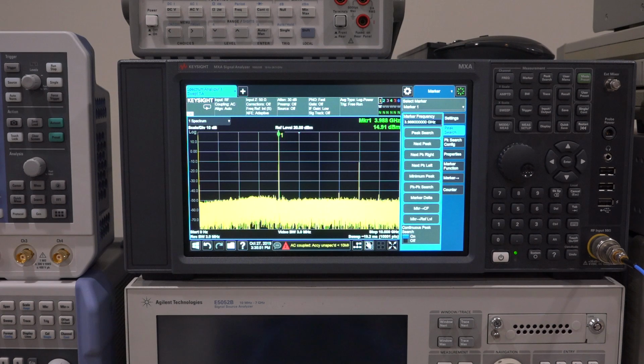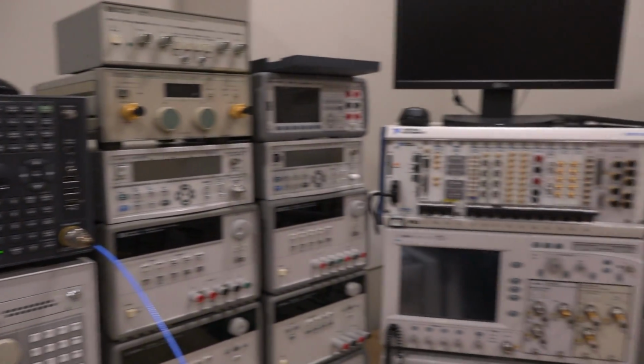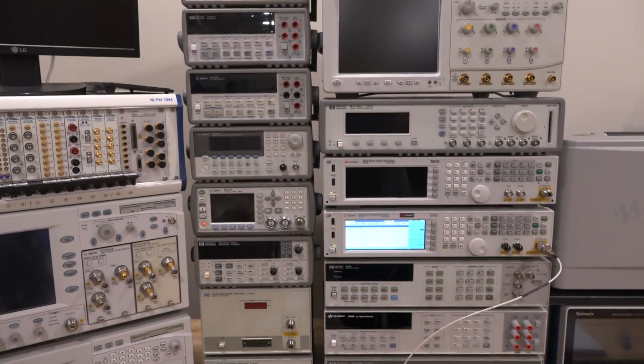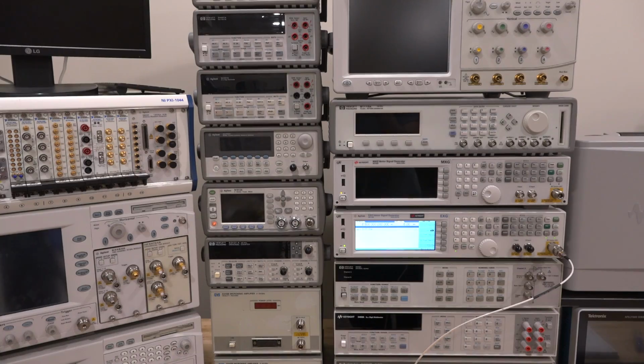I think what we can do is we can change the reference and apply an FM modulation to the reference to the LO board. And if it is correct, we can identify which voltages of the VCO are intended for FM tuning. So we can go ahead and try that. I'm going to do this, of course, on this instrument right here. So let me go ahead and set that up.